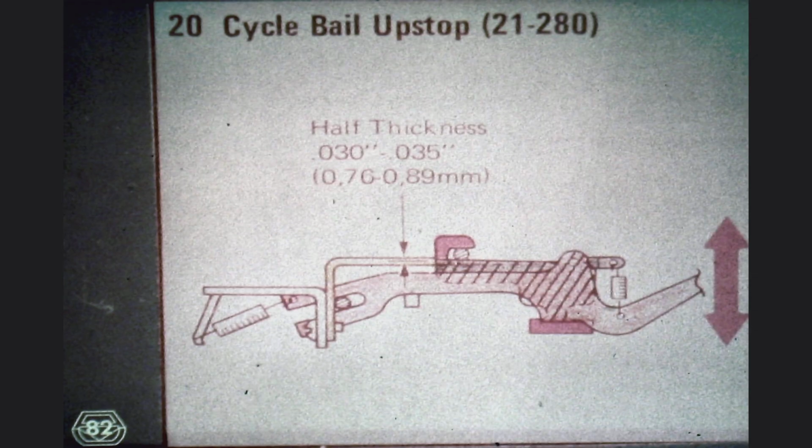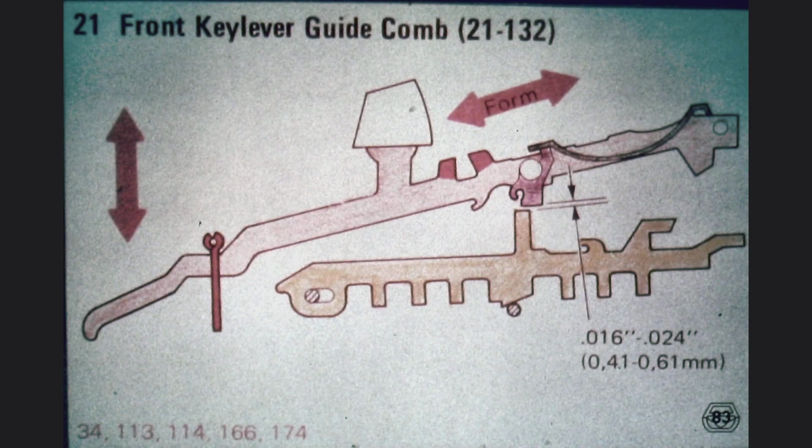Using the previously established rest position and the latch down position of the interposers, notice that thus far we have only made adjustments underneath the character interposers. Now we use the same fundamental adjustment of the rest position of the character interposers as our reference point for the adjustment of the keylever up stop, which we removed a bit earlier. At first sight, this adjustment appears rather simple and final, but not so.